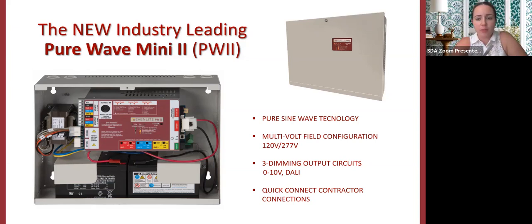Kyle, I'm going to interrupt you, sorry, for 1 second, just because for people who do not do as much lighting controls, typically what happens on a project, when you use an inverter or generator, is you have a lighting controls room controller or power pack. Then you have an occupancy and daylight harvesting sensor, depending on if you needed daylight harvesting or not. And then you have override switches, and then you'll have to add a shunt relay for each circuit for the emergency lighting. And that shunt relay acts as a sensing link.